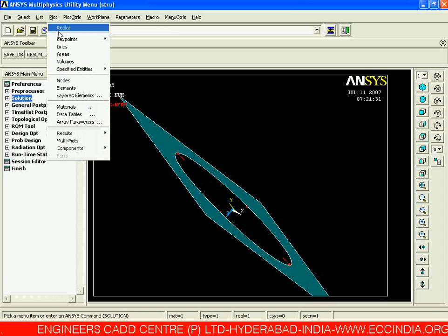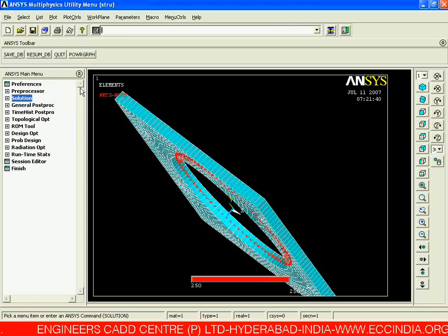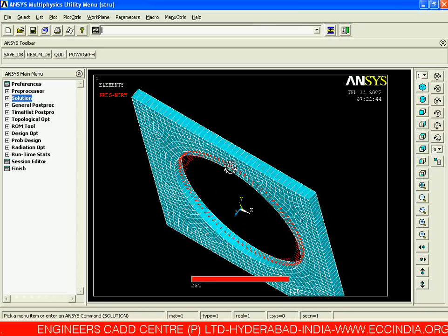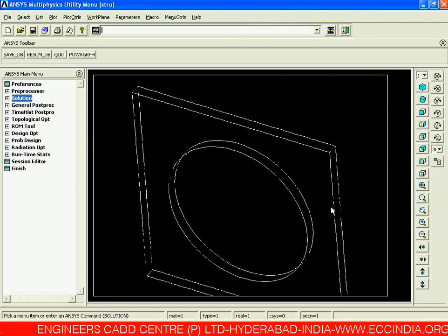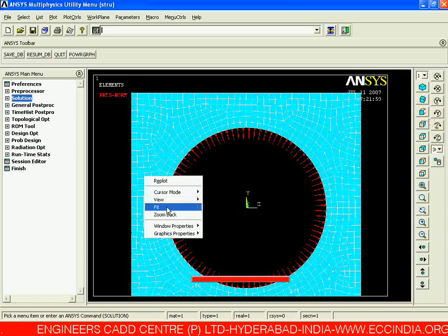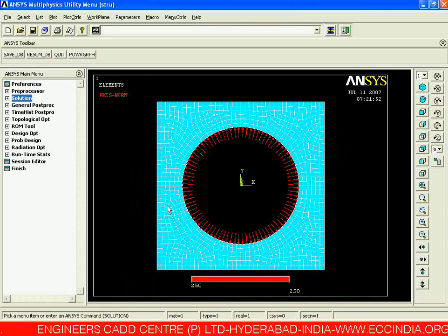If we are going over here and just saying that I need to plot for an element, we are getting our thickness back. That means all the values whatever we are applying over here in a thickness column, all are going to be assigned with respect to our finite element entity, not with respect to our geometrical entity.